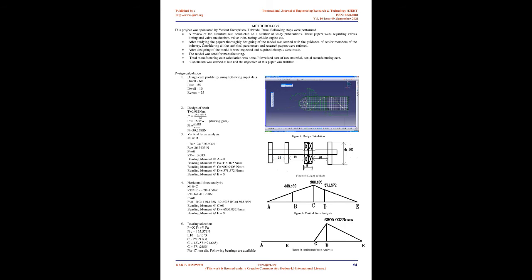2. Valve timing and valve lift control mechanism for engines, Kazuhiro Nagaya, Hiroyuki Kobayashi, Kazuya Koike, 2006. A novel sort of engine valve control system has been developed, in which electric motors regulate both valve lift and valve timing. Planetary gears are used in the valve timing control system's mechanism. The timing pulley, which is powered by the crankshaft of an engine, is the outside gear. Inside the pulley are two planetary gears.